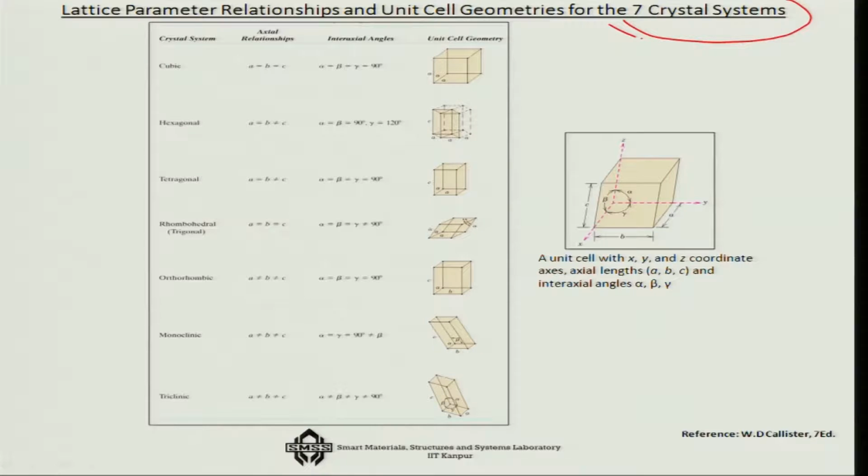The 7 basic crystal systems, and if you summarize, you will once again see each one of them, with the cubic structure having the highest degree of symmetry and triclinic having the lowest symmetry in the structure, where neither A, B, C are equal, nor alpha, beta, gamma are equal or orthogonal, etc. So, that is a kind of generic map of everything together.